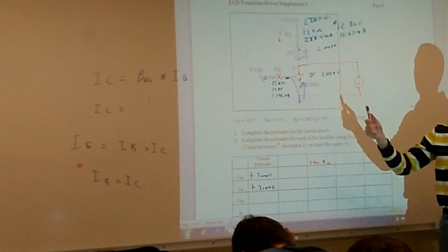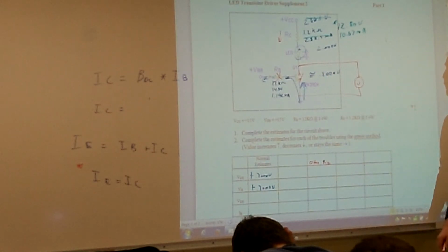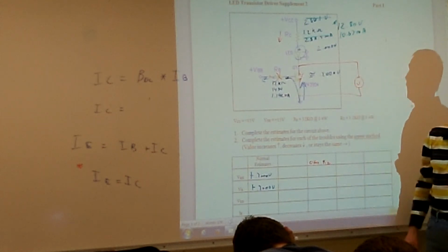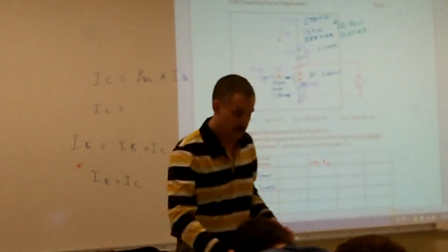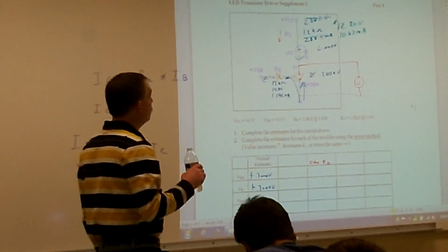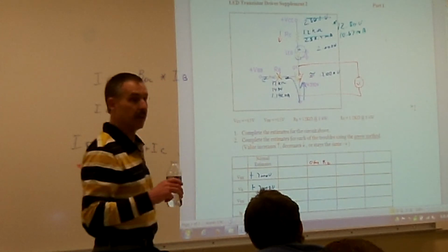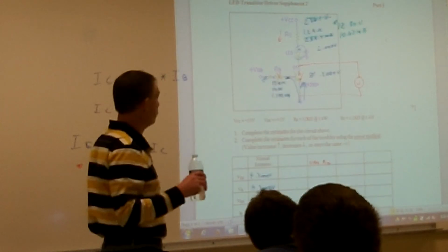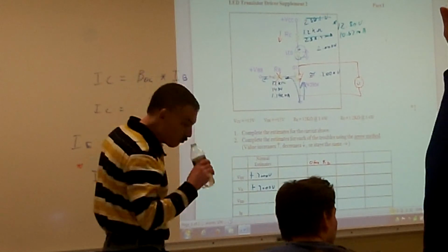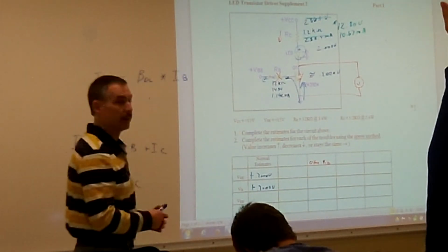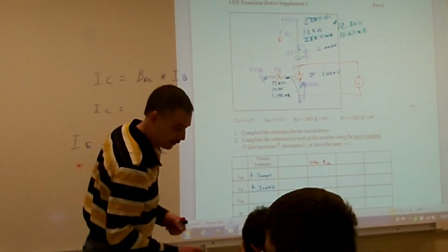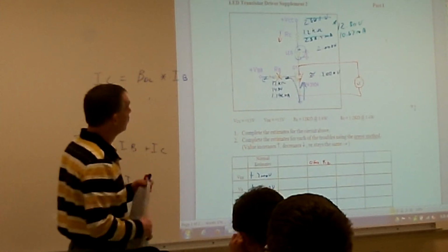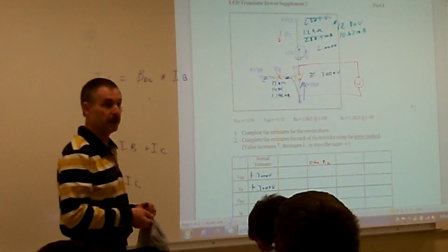Ideally we could say 0 though. Yeah, you're right. Ideally from C to D would actually be 0. But when I put a voltmeter in there, then who knows what's going to happen. So theoretically CDE would be 0, but I would put a little question mark on there with a note saying, what about my voltmeter? Theoretically 0. Practically, you would probably end up measuring some voltage.